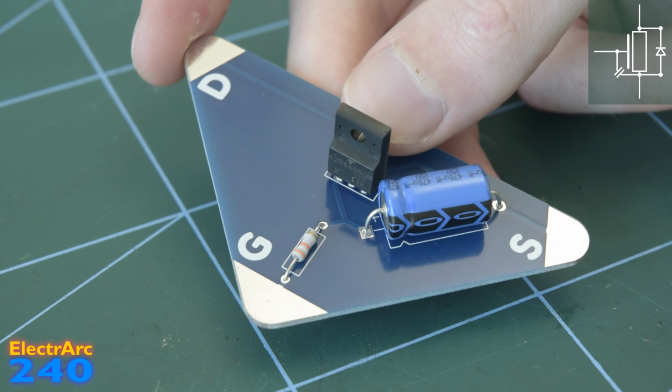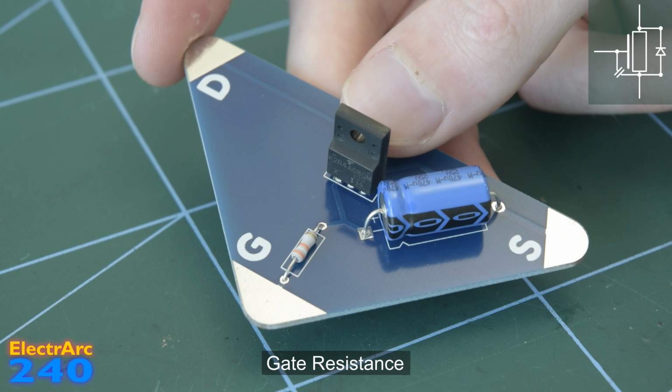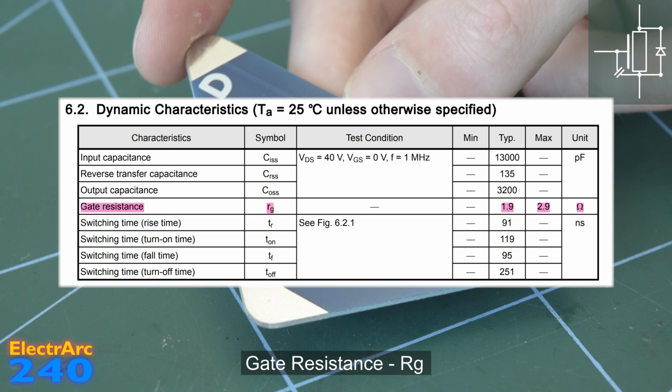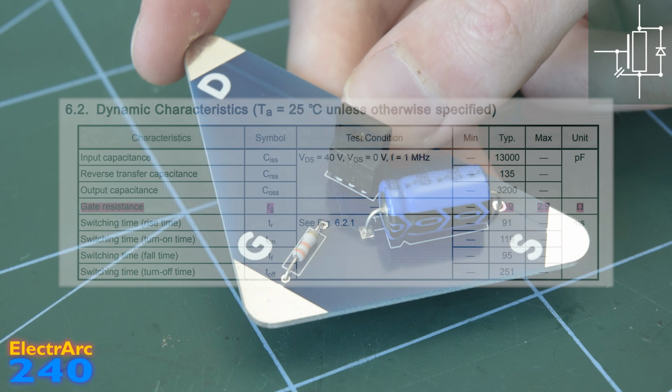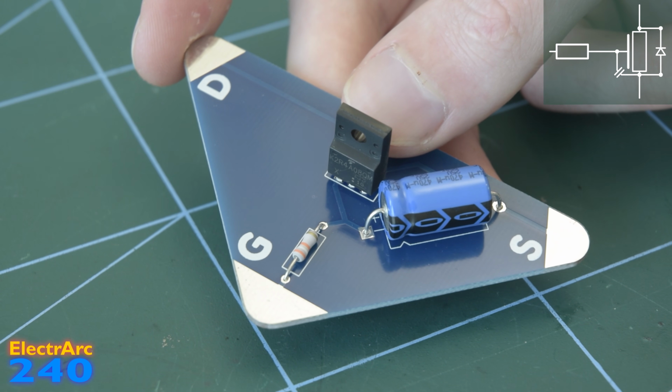Once again, it's not that simple, sadly. You might have noticed this resistor. This is the gate resistance, and it's internal to the MOSFET, so there's nothing we can do about it. You can see it here on the datasheet. This resistance limits how fast we can charge this gate source capacitance, and in almost all switching circuits we will actually add more resistance externally, for reasons I'll get into later.